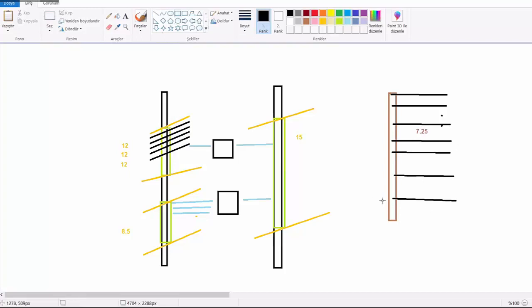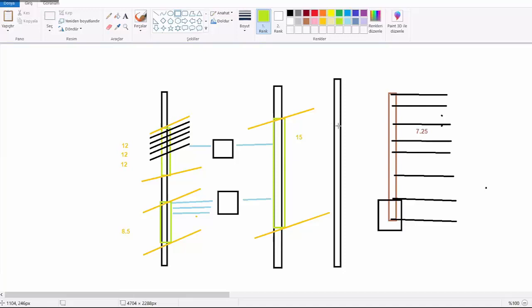But what are we going to do for the rest of the 25 centimeter? If I select acceptance percent as 25%, then that means, okay, if it's 25 centimeter, create one additional level for that. But if it's less than 25 centimeter, don't even bother. Don't even create another level for that. Because I'm getting 25%, now I will create another level for that 25 centimeter. Also, if I have a borehole and a really small 25 centimeter level, we are also going to create one composite level for that 25 centimeter level as well. So in here, whatever is grade, it's going to be shown also.